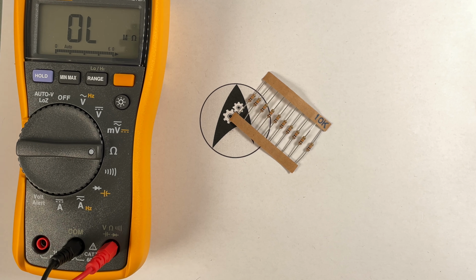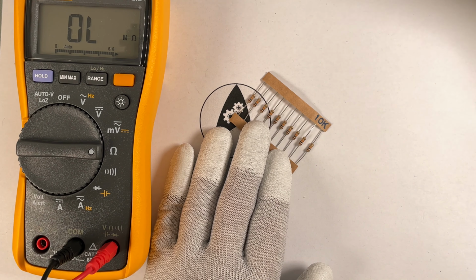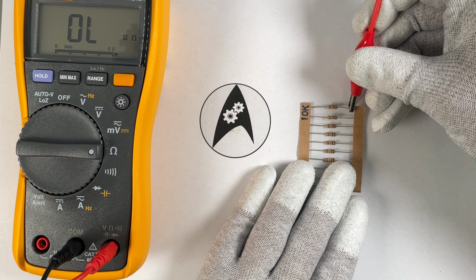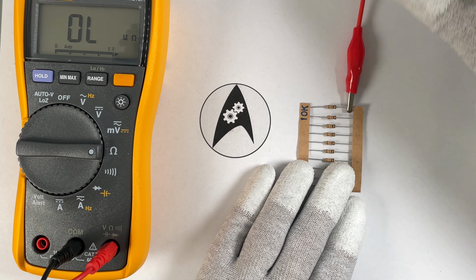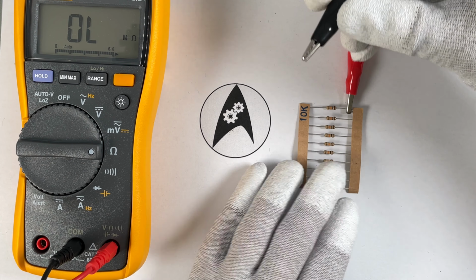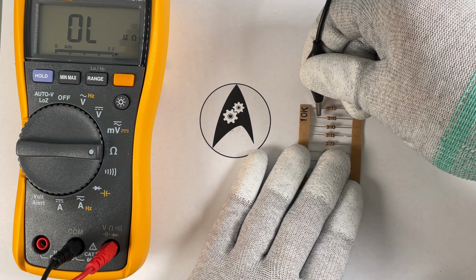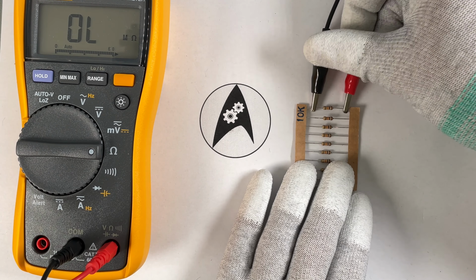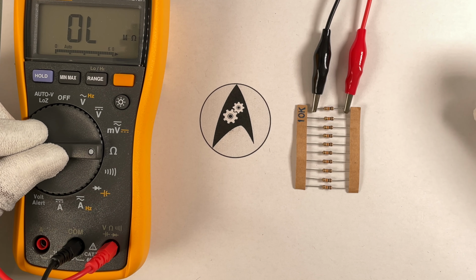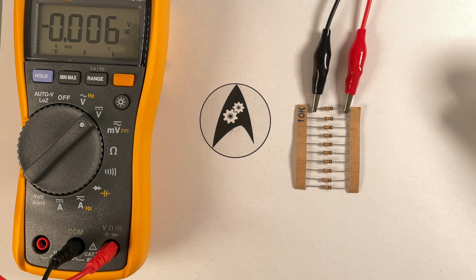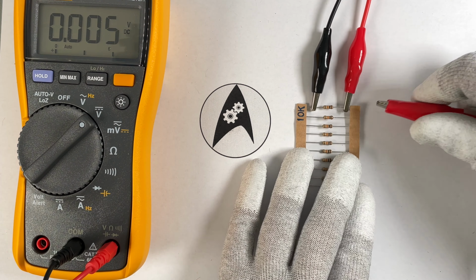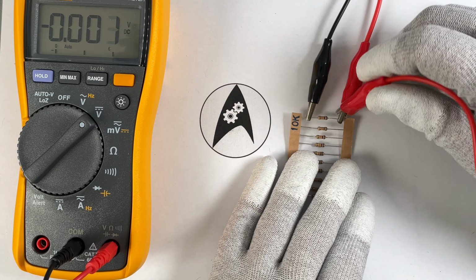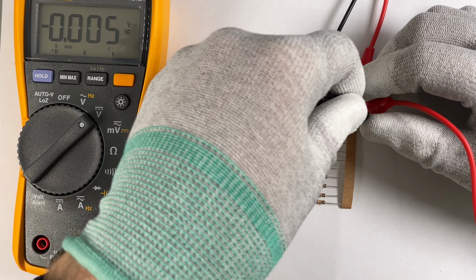Now, in order to test the validity of Ohm's law, we need to hook up a power source to this resistor here, and the power source is an adjustable power source, which currently is set to a voltage of 5 volts, which is what will drop across this resistor here once we connect these clips leading to the power source and switch it on. As of now, it's still switched off. And what we will also do is set this amp meter here to voltage measurement, connect the red lead to the positive terminal of the voltage source and the black lead to its negative terminal.